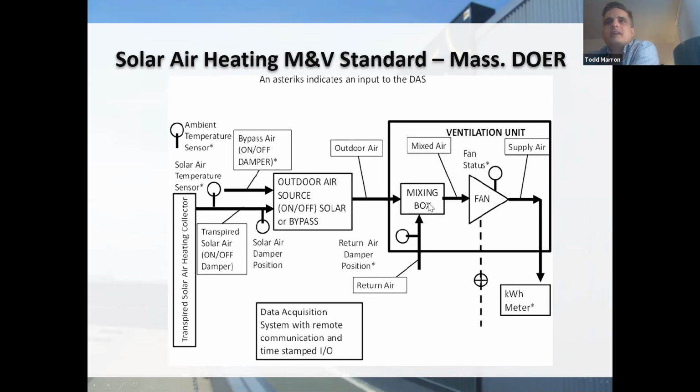And then very often you've got some sort of mixed air within that unit. So you've got recirculating air coming in and out of the unit, and that's controlled by a damper position. So we need to tie a signal to that damper position, and that signal needs to correlate to a TAB report. So when you're producing the test adjustment and balance report at commissioning, you need to do it at every single damper position, so 0 through 10 on that mixed air damper, so that you're always quantifying the precise amount of fresh air coming into the system. And so now when you've hard coded a CFM value to each damper position for the return air or mixed air, again, if that's present, in a high-rise multi-res building there just simply isn't mixed air, it's just 100% fresh, or many other buildings, then you're able to achieve that CFM value. That's hard coded, and in it goes. And then of course you would mathematically divide by an assumed efficiency of that ventilation unit.